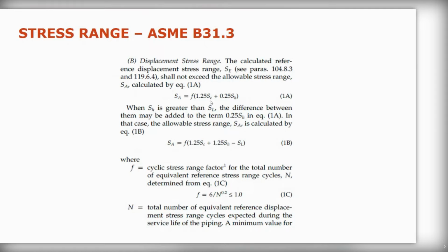And that may look strange, and you may say, well, how is that? Why is that happening? But that is the point, because for those stresses, you could go all the way to yield. As long as you accommodate the displacement and then stop, it will not in itself break the pipe. It will just change its shape, but it will stay in that position.